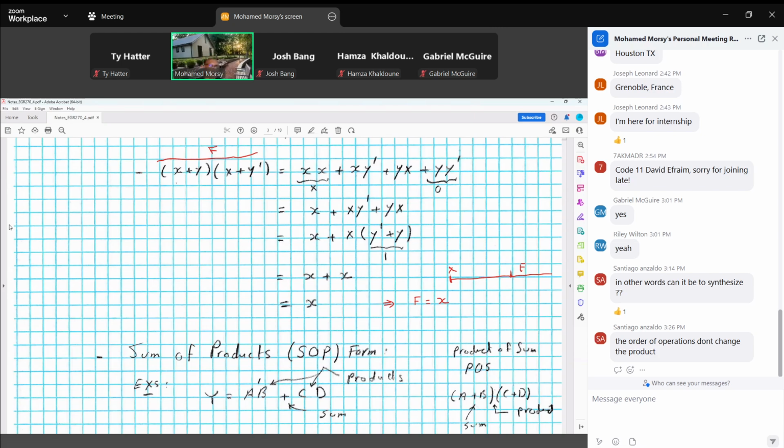Sometimes, as we will see later, you have certain inputs at the input of the system. They came from other stages before, but they don't have effect on the function of the last component. So this input is called "don't care". If you take it 1, the same result. If you take it 0, the same result. So here, it doesn't matter. It has no effect on the output.